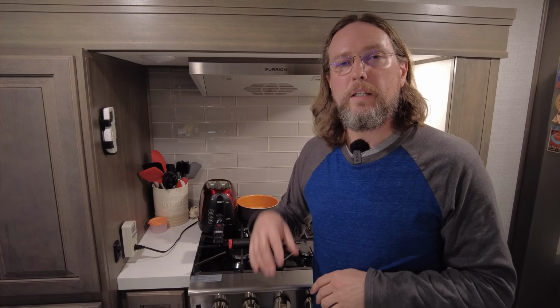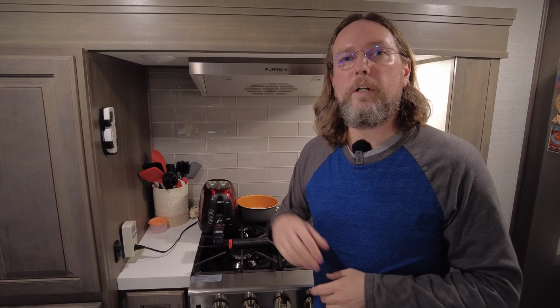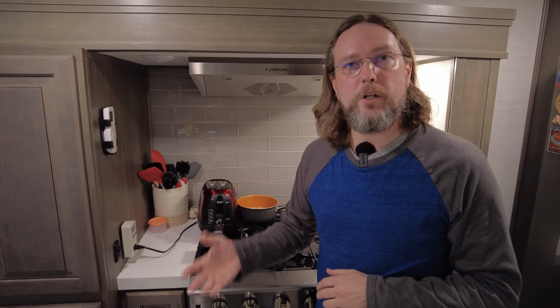And that's why I said earlier that I don't really like using that label plate method, because it's not always entirely accurate. This toaster's running about 100 watts less than what its label plate says. Now, in all fairness, and I just put two and two together in my head, this toaster is a few years old, and I've actually noticed recently that it takes longer to toast my bagels, my bread, whatever I put in there. It's taking a little longer than it used to, and I think it's probably just age. Now that I can see that it's drawing about 100 watts less than what it's rated for, I'm thinking it's just deteriorated over time, and that's why it's taking longer to toast all of my stuff.